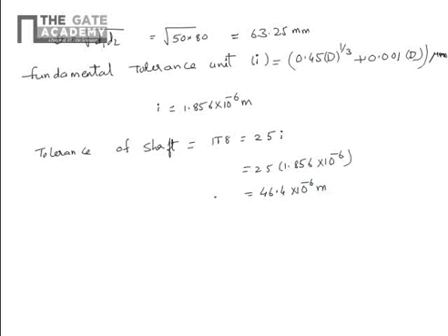Next, fundamental deviation of shaft he has given. Fundamental deviation of shaft is equal to minus 5.5 into D power 0.41 micrometers.